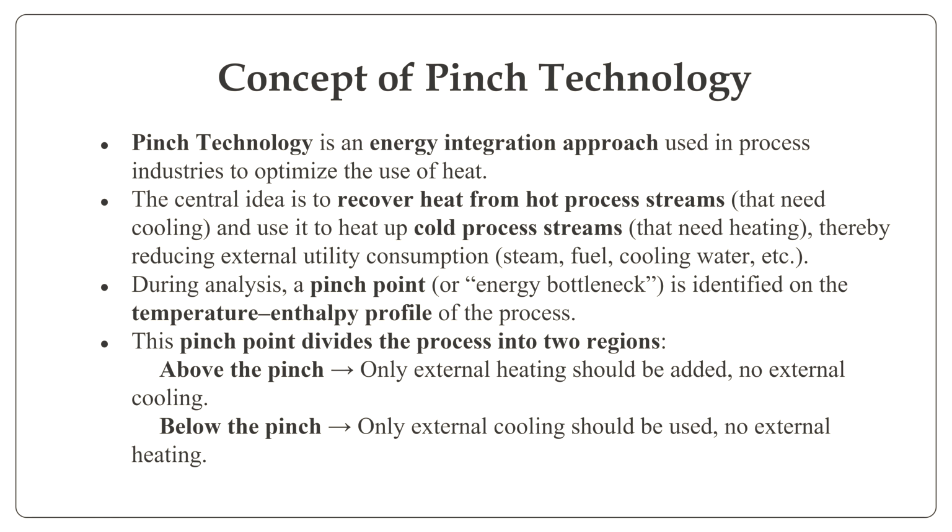Concept of pinch technology. It is an energy integration approach used in the process industries to optimize the use of heat for recovering the maximum energy. During the analysis, it determines a pinch point. The pinch point is nothing but the minimum temperature difference between the two streams. It is also called the energy bottleneck. It identifies the temperature enthalpy profile of the process. Above the pinch, only heating is used, with no external cooling. Below the pinch, only external cooling should be used, with no external heating.